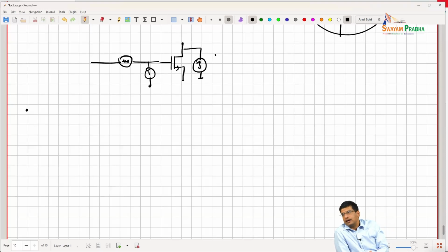If you are in an application where the antenna impedance is up to you and you can control the interface, by all means, it is perfectly feasible to change the impedance of the antenna so that it is presenting Zs opt and you are power matched at the same time, right?